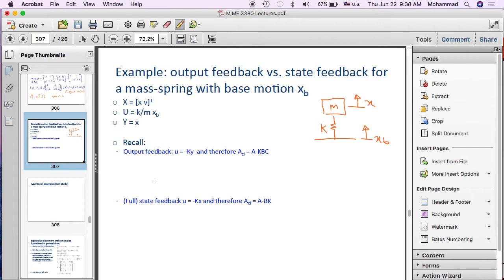So the assumption is that x, the displacement of the mass, is measured from the static equilibrium. So weight has been canceled with the initial deflection of the spring. So when you draw the free body diagram, weight doesn't come into play. So the free body diagram M and there is one force of spring here, and this is displacement x.